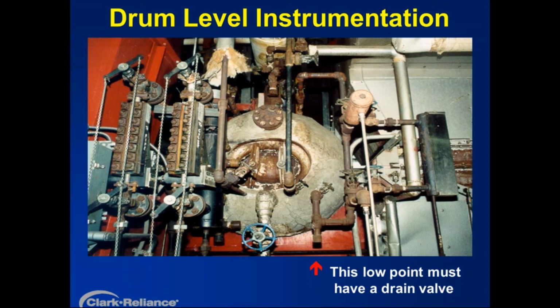Operator happened to be out on the floor, looked at level just about to flirt with low water cutoff, and they were seeing above normal on the two transmitters. So what they ended up doing was blowing down that trap through the drain pipe that you see on that conductivity probe column way off to the right, and then immediately a bunch of particulate blew out the drain, and both of those transmitters responded with a much lower, more accurate level.